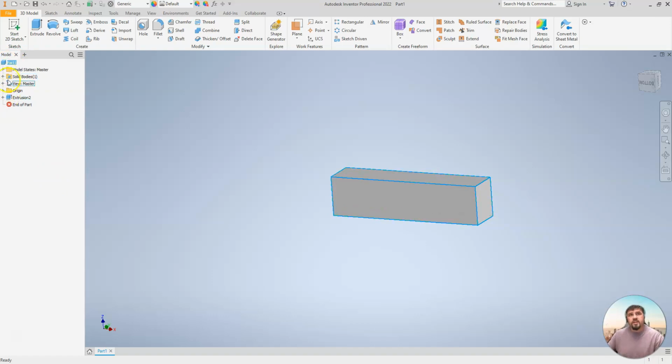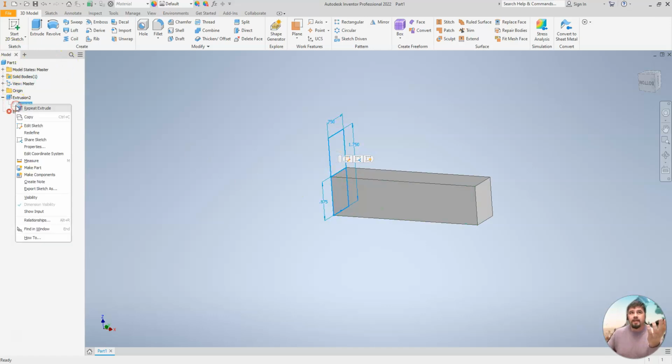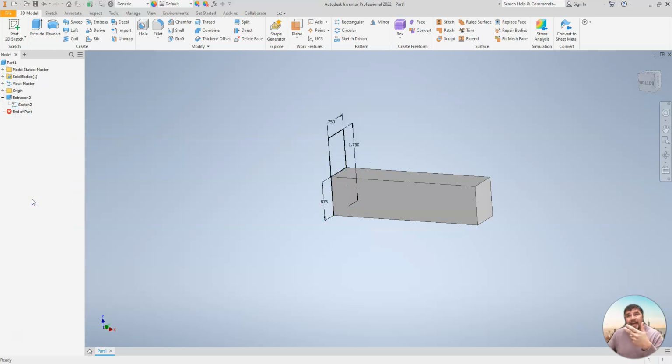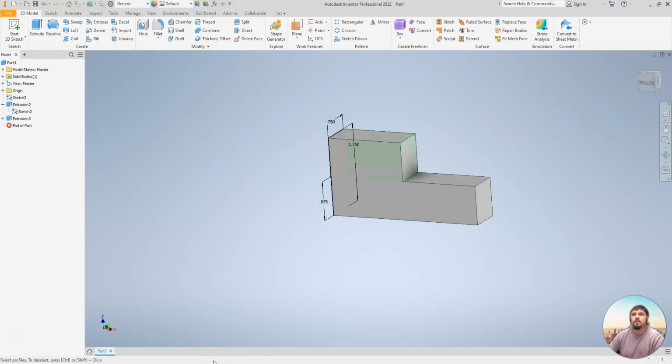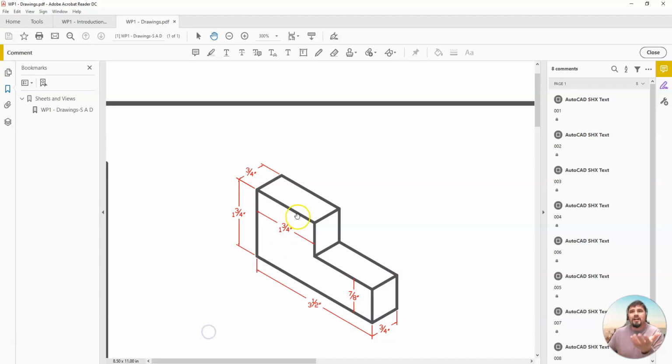Either way, you're going to see all the number of extrusions that I have as I project through this object. But underneath each extrusion, if I click the arrow, I'll see the original sketch that it came from. I don't want to draw this shape again because I'm working off the same sketch going 2 different extrusions. So I'm going to right click that and bring the visibility back, then click extrude, and bring that one forward. Now that one's only supposed to come forward 1.75 inches. Boom. Now I have my shape, but I've just drawn it a different way.